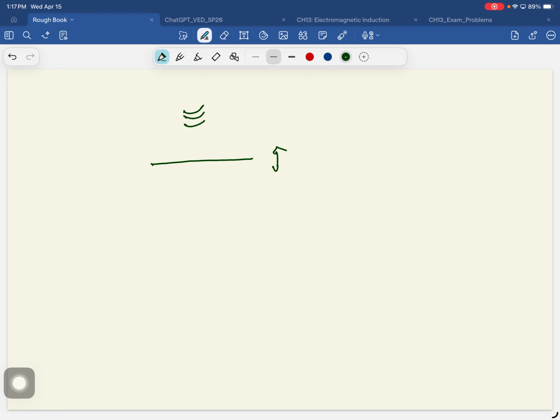So it's like you hold up a paper and talk loud, and this paper is vibrating. Now what's your job? You want to convert that vibration of the paper into an electrical signal. How do you do that? Now you know all the ingredients. The first thing you need to do is attach a magnet to it. So as this thing vibrates, this magnet will move.